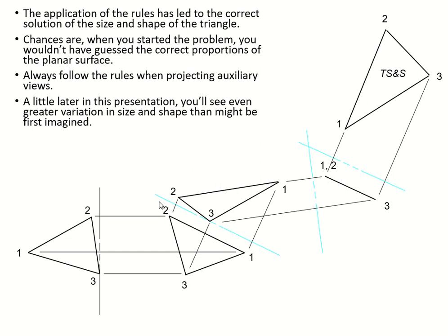We didn't have a true length line, therefore we have to make it up by getting a line parallel to one of the edges of your middle view. And that second reference line comes from the first reference line by keeping the same dimension. Going from here to here is difficult because of the front view and that's your right side. And you have to consider the depth behind this edge, okay? So it got raised instead of flat like this. So going from here to the first parallel line to your second fold line is very important for you to study this problem.